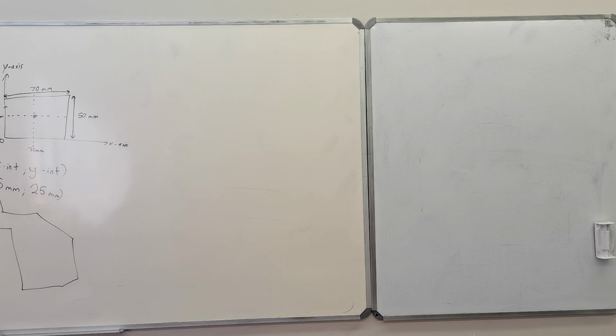But what they're basically saying is, whatever the area of that shape is, multiplied by, if you're looking at your x-axis, you will take your x distance. If you're looking at your y-axis, you will take your y. We're working on area now. The moment of area.